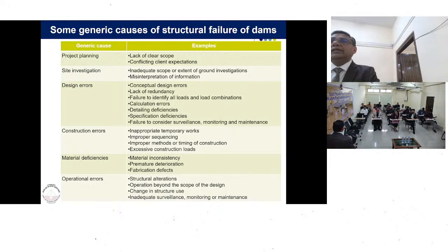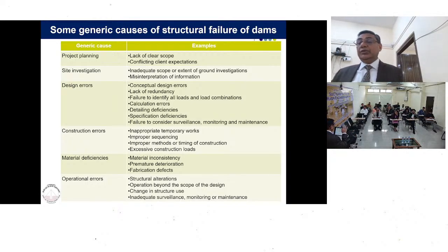So then the investigation started for the earthen dam. Borrow areas were identified, materials were tested, everything was completed. Then came the planning of the construction of the dam. So a visit was carried out there. The agencies involved were Central Water Commission, CSMRS, and GSI. GSI looks at the geological formation, Central Water Commission looks at the designs, and CSMRS looks at the borrow area materials.